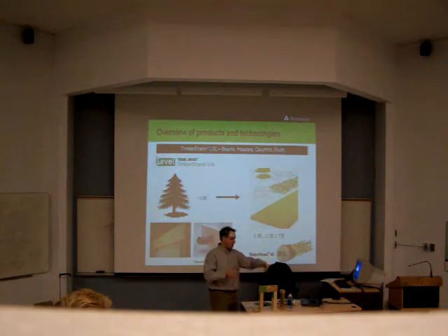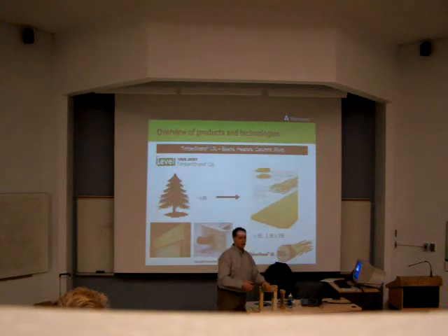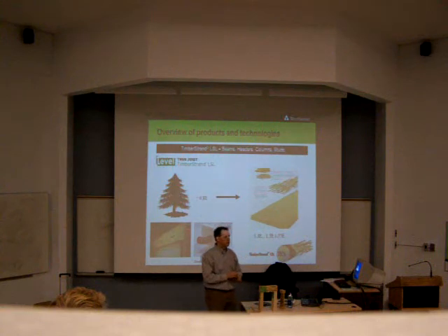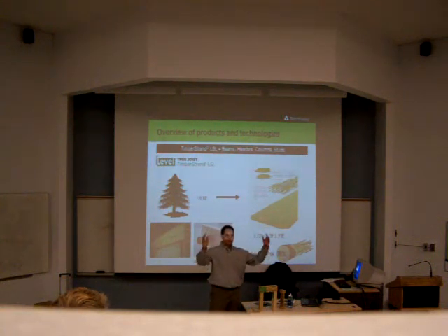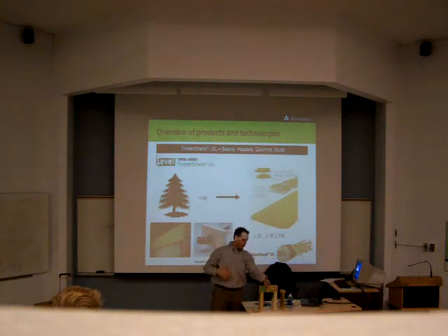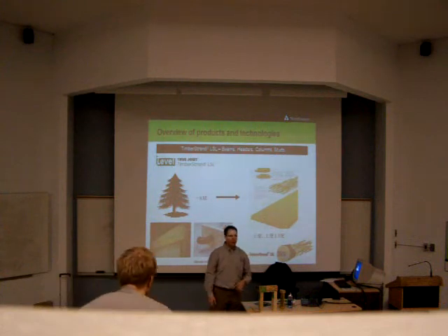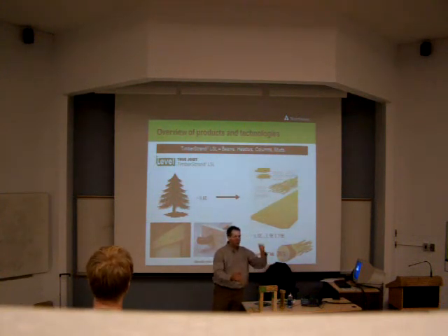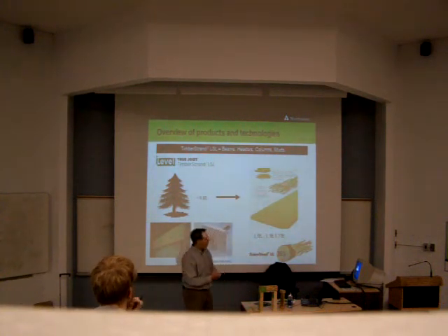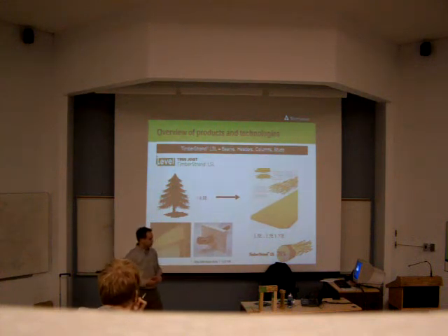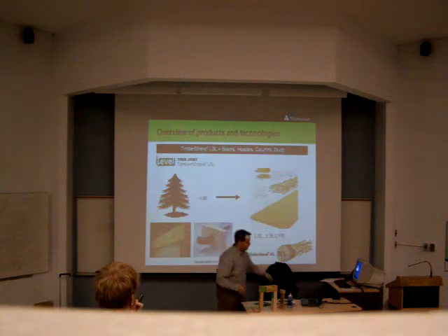But if you have a shorter span, but really heavily loaded, then shear or crushing becomes critical, becomes the real governing factor. But if you had a 6-foot patio door that had a big point roof from a girder truss up above, it's not how much it's going to bend that's going to be really governing, it's how much it's going to want to slice off out of there. Okay? Or how much bearing length you need, because there's so much load there. So that's where timber strand really shines. Okay? So lower E value, but higher in other respects.